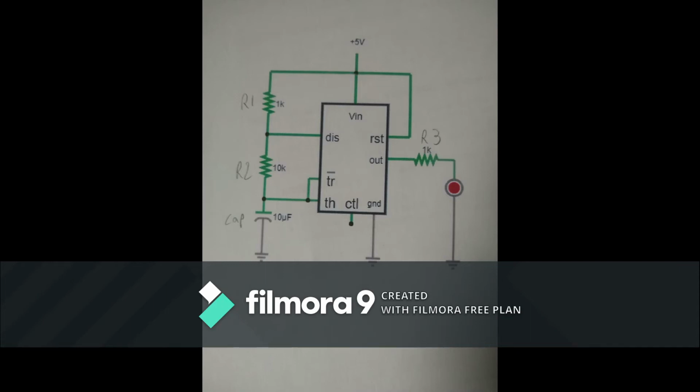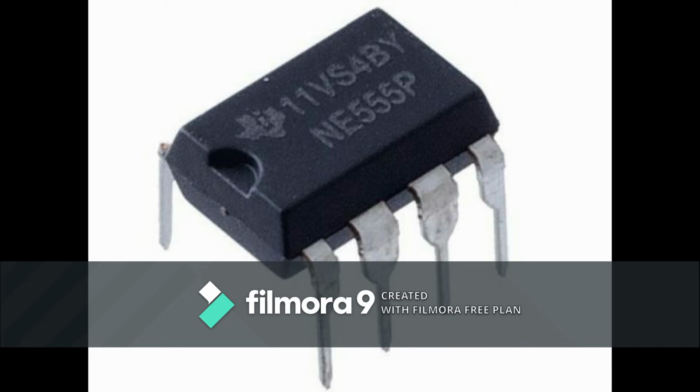We are doing the 555 timer as the astable multivibrator. Now we could have had it set up as a monostable or a bistable multivibrator, but this is probably one of the simplest to get into. Because we picked the astable multivibrator, we have the only circuit that doesn't require any push button inputs to turn the LED. Now let's talk a little bit about these 555 timer chips.